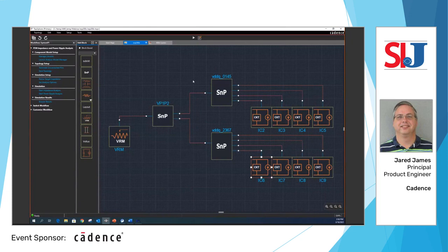We have various building blocks, from subcircuits, SMP blocks to ideal elements, layout elements, VRMs, Voltus blocks, and then an IC block. The IC block is usually what you start with, and it describes what your on-die PWL and on-die power domain look like.